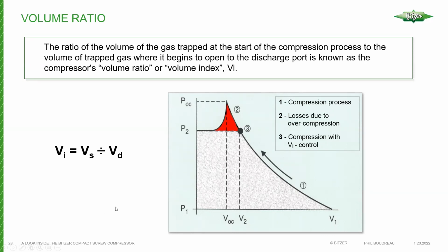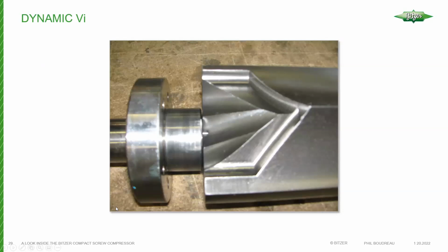So the reason why I'm telling you all this is since we're talking about capacity control, and I apologize for this photo. I take full responsibility for it because actually I'm the guy who took the photo. But it highlights something interesting with the slide valve. This is the discharge end of the slide valve. You can see that it's actually machined out, okay? And this part of the slide valve will allow for a somewhat smaller discharge port here. It may be difficult to imagine, but the slide valve is part of the discharge port.